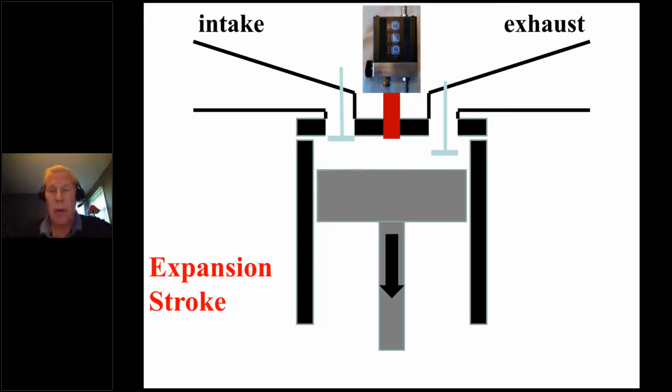I'll tell you why this is important. Imagine you're working on a running engine, a 4-cylinder, and you're in one of the 4 cylinders, so the other 3 are still exhausting, or you're in half of a V8. The exhaust pressure pulses from those other cylinders are now seen in the cylinder that we are analyzing. That's an example of airflow dynamics. Now that occurred because the exhaust valve is open in this case. So that's something to keep in mind as we move through this discussion and in general when you perform this type of analysis.